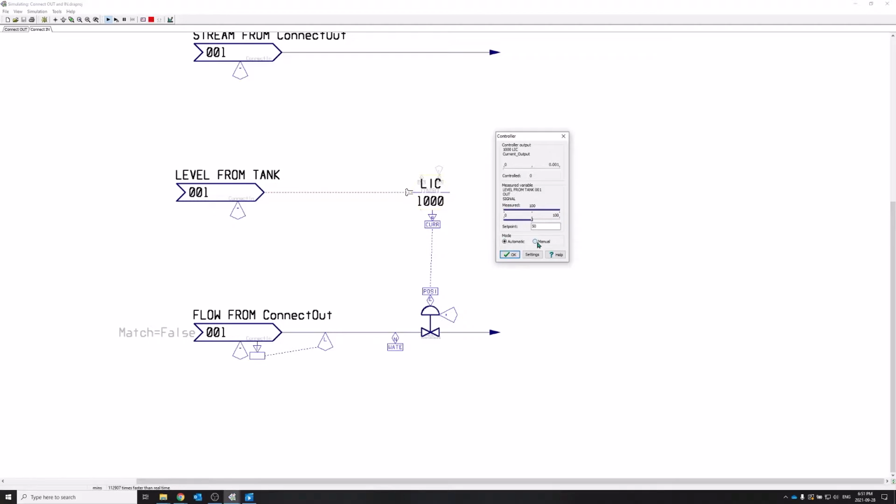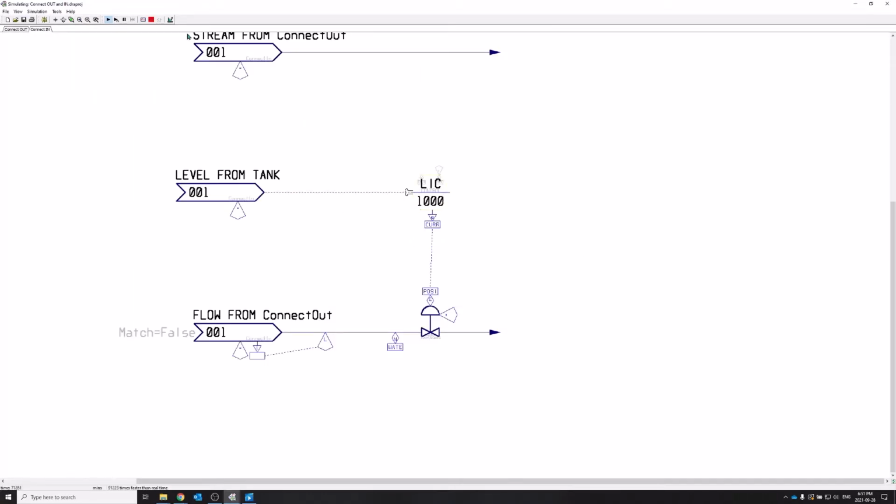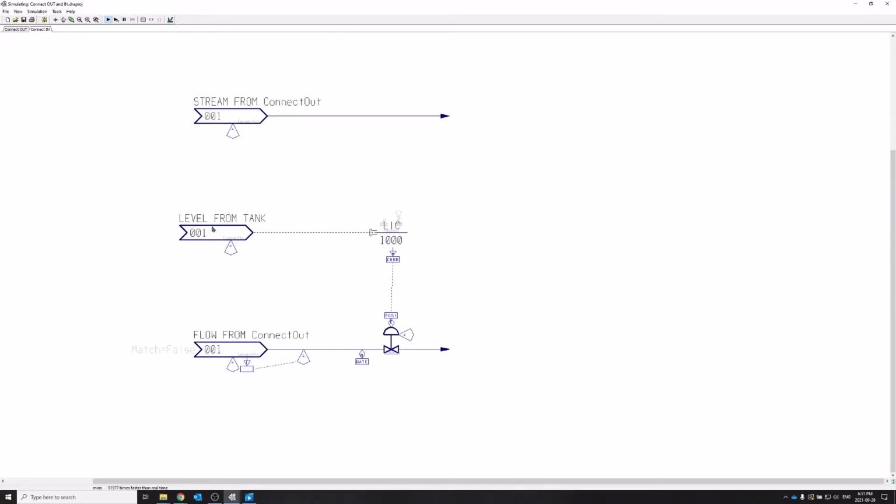And if we go into manual mode and sort of increase the opening of the valve, let's jump to 50, maybe 50.9. We're getting a bit of action here. So we made a correct guess here. So now we're actually already in the stage where we're tuning that valve. So 50.5, we're getting level. So now let's hit pause.